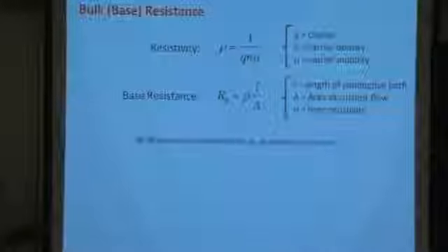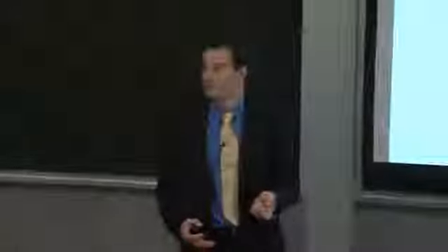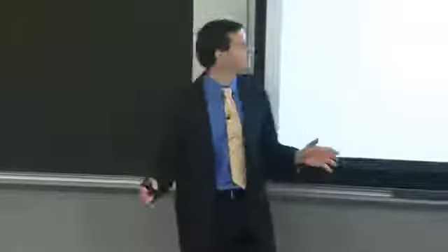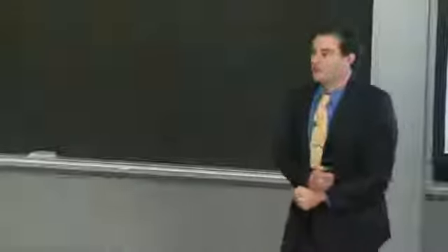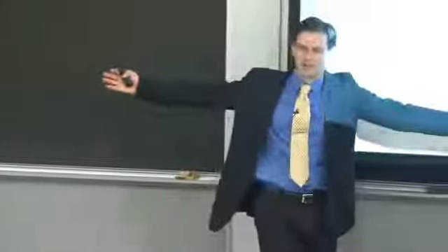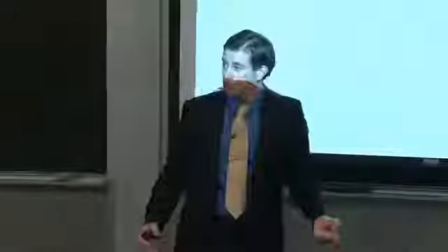So to minimize base resistance, we want to have a very thin solar cell device. But wait a second, if we make it very thin, then what happens? Less absorption. So we have to make it a certain thickness to get a good enough absorption. Then we can compensate. If we still need to drop the base resistance, we can increase the area of the base. Right? And so far, that makes good sense. There's nothing else tugging for the area to be in the other direction. Right? So we can make this solar cell infinitely large, thick as we want it to be to absorb all the light. Great. OK. Hold on to that thought, because we're going to have another constraining parameter that pushes us in the opposite way in a few slides.